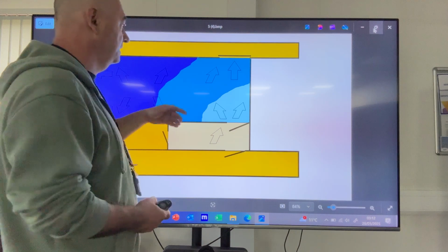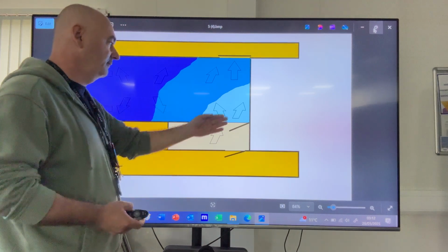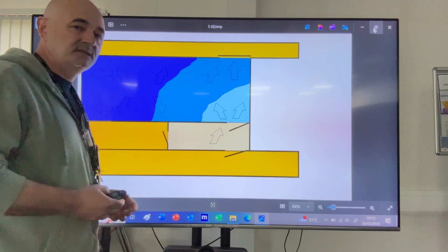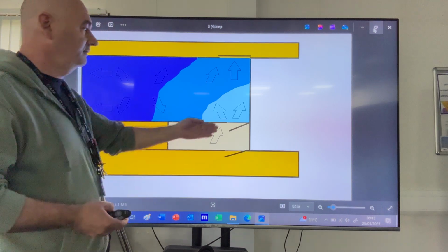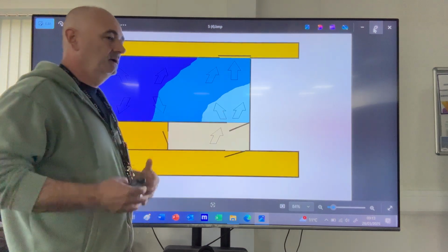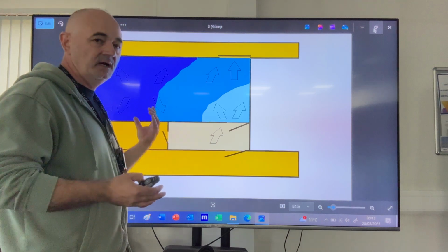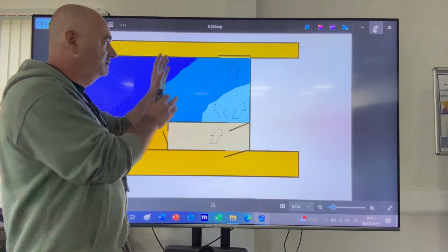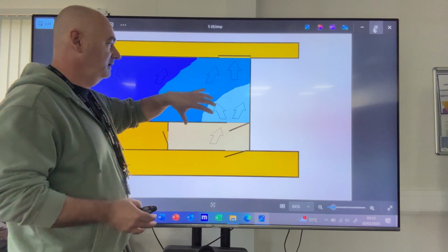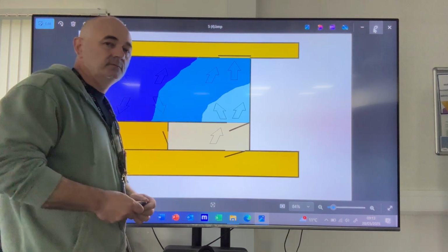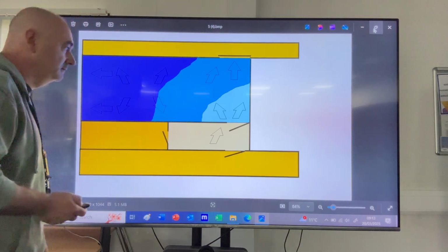If I have two sensors, I could read the average, but if I have only one sensor, it doesn't mean the entire room has this temperature, and this is debatable. I want to make sure that if this corner is deemed to be the reference point for the entire room, then we have to change the ducts and the outlets to compensate for the hot air which comes from the other room. This is very important.